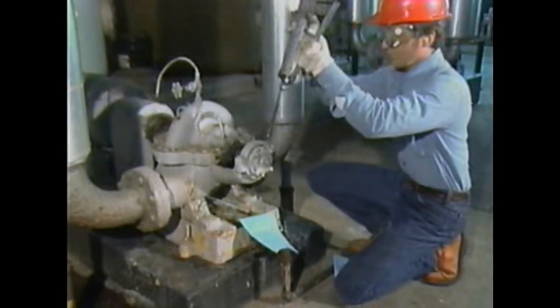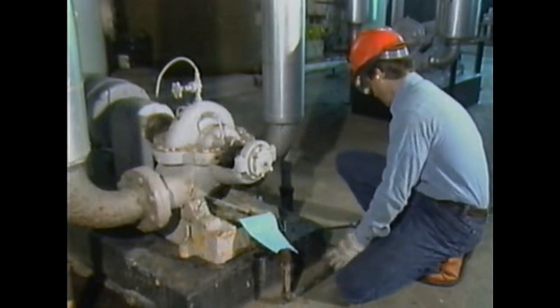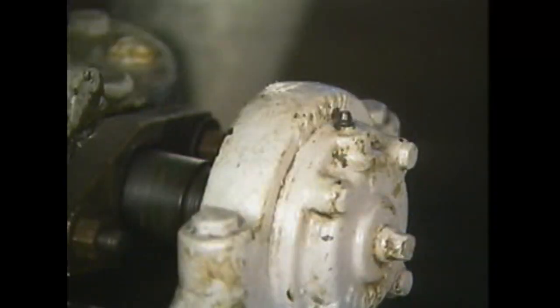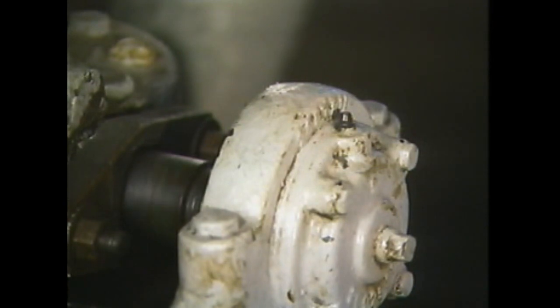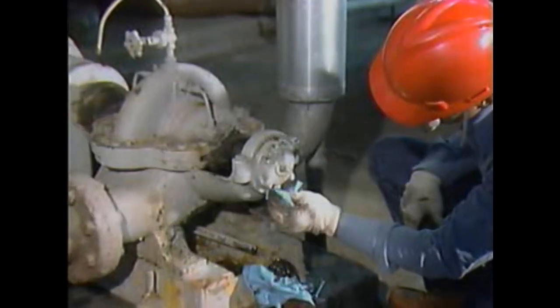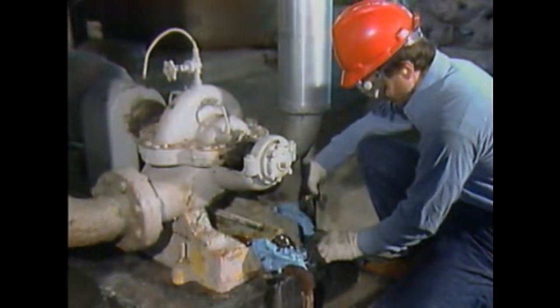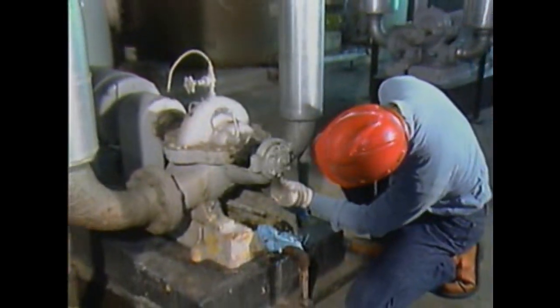Next, disconnect the grease gun from the fitting and wipe the fitting clean. Then allow the machine to run for a few minutes with the drain plug still removed. As the machine operates, excess grease will be forced out of the drain hole. After a few minutes, wipe the drain plug clean and put it back in the drain hole.